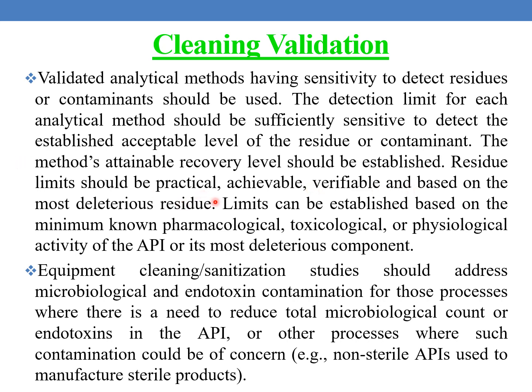Residue limits should be practical, achievable, verifiable, and based on the most deleterious residue. Limits can be established based on the minimum known pharmacological, toxicological, or physiological activity of the API or its most deleterious component.